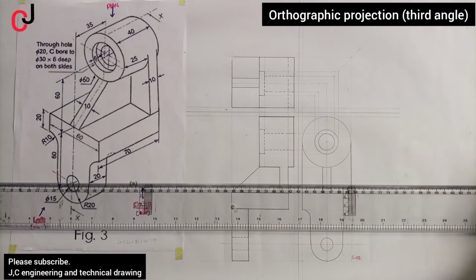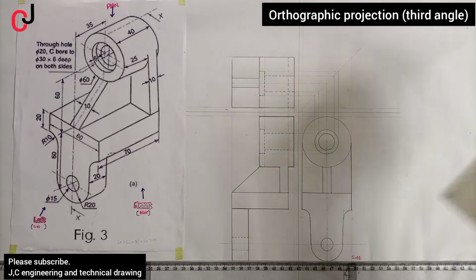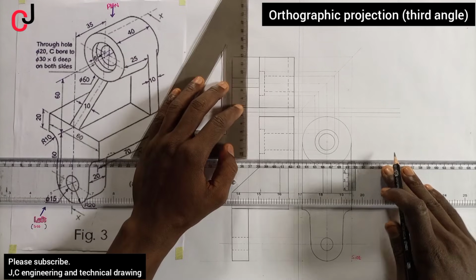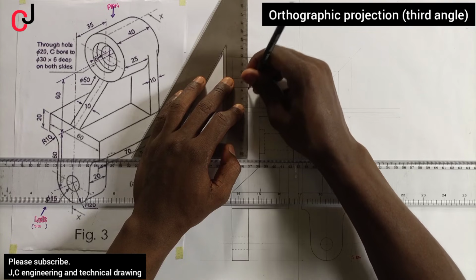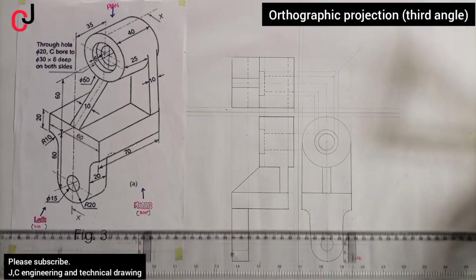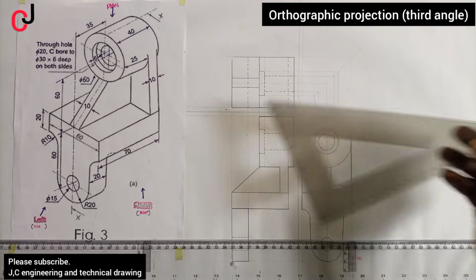Now the next thing you do, you check if you are done. So from our front view here, you project construction line straight to pass through the plan. You indicate it with a broken line, showing that there's something passing through, showing that this distance of 20 diameter is passing through, so you indicate it with the hidden line.